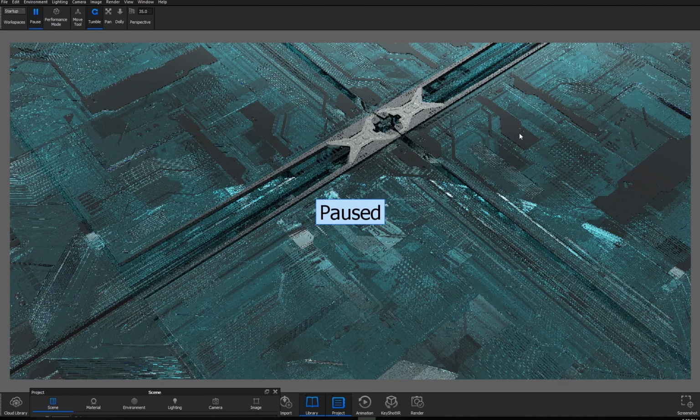Like that. You can see I got the black glass over there and transparent glass here, essentially because of the amount of ray bounces I had set up in my scene. I don't have enough ray bounces over there, so it's all looking black, but I have enough here, so it's kind of transparent, but not really.